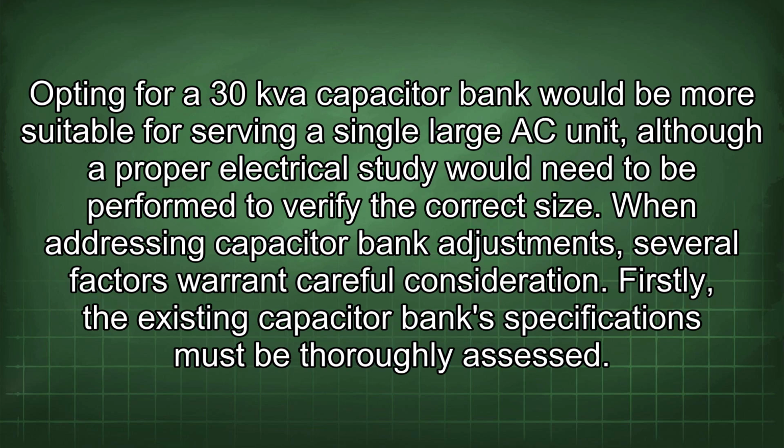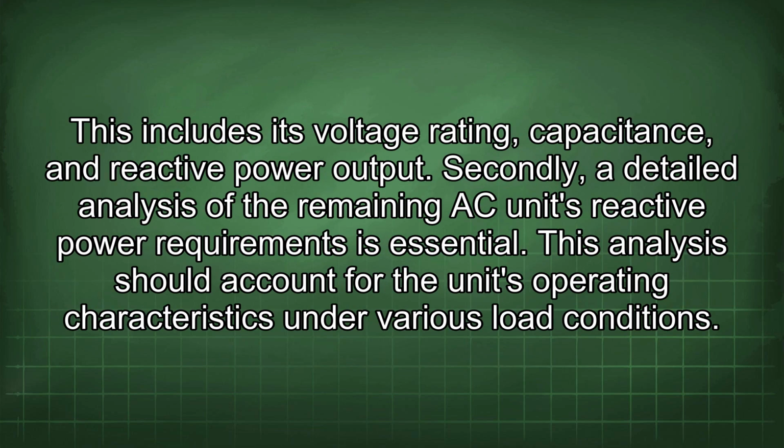When addressing capacitor bank adjustments, several factors warrant careful consideration. Firstly, the existing capacitor bank specifications must be thoroughly assessed. This includes its voltage rating, capacitance, and reactive power output. Secondly, a detailed analysis of the remaining AC unit's reactive power requirements is essential. This analysis should account for the unit's operating characteristics under various load conditions.